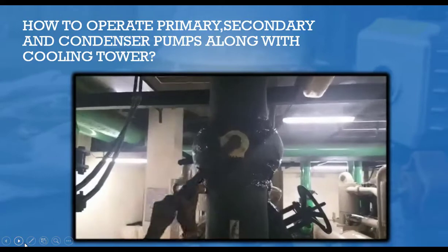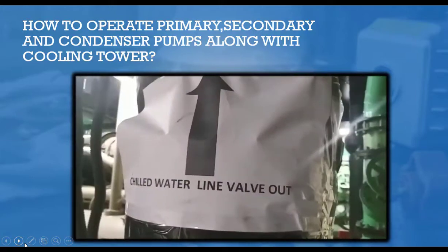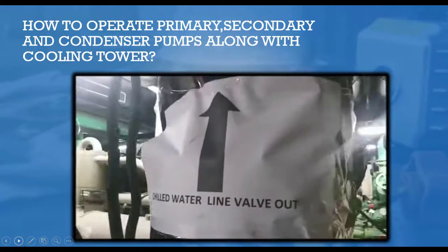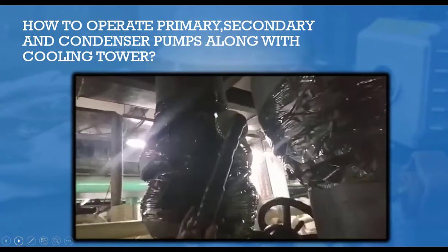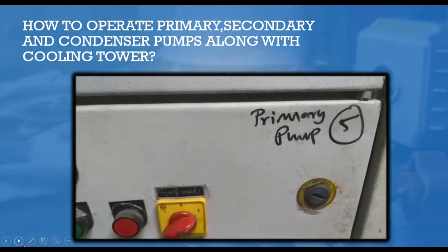If you have different zones on the secondary side, ensure all the secondary side chilled water valves are opened in all the zones, like banqueting and guest room.